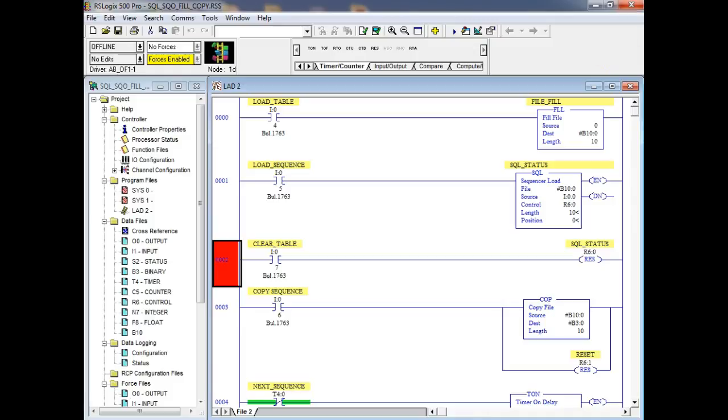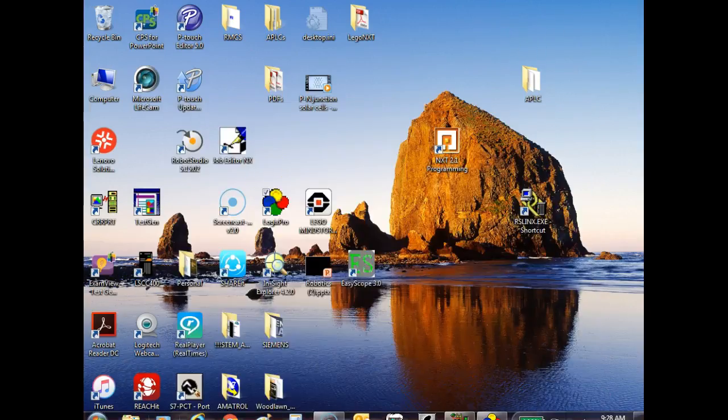So when I load my sequence, I'm getting them in from input 0, word 0. Okay, y'all understand that? Well, I'm not using all those bits. I don't want all those bits to be sent to my output port. So what bits do I want to see? I can actually do my mask. I should do it a little different. It would still work.